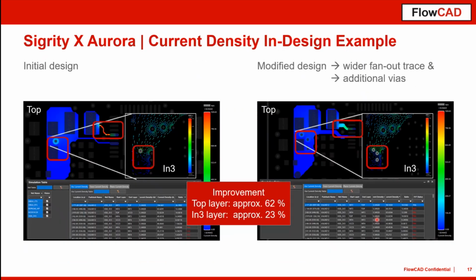On the other side, here is the output of our voltage regulator. We can see this output pin. The whole current goes over this inductor and directly uses only one via in this case. That means this one via has to carry the complete current for this power distribution network. And then you can say, oh, that also might be overloaded. That is shown here in the table below, which automatically calculates the current distribution in all those vias.